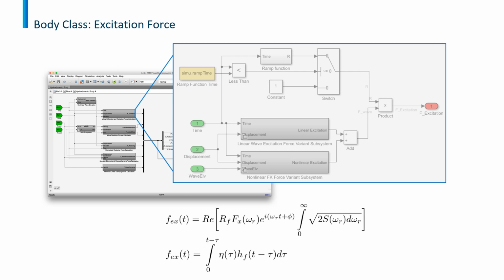The general equation of motion for a body experiencing hydrodynamic effects is represented using the Cummins equation. The screenshot on the left shows the implementation of the Cummins equation in WEC Sim. The different contributing forces are the excitation force, the radiation force, and the hydrostatic restoring force. Additional forces like the Morison element force, the viscous damping force, and any other linear damping force can also be included.